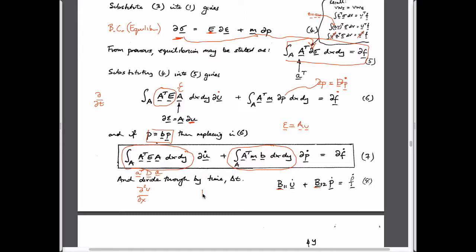Our relationship which defined advective flow was something like the integral of A transposed times velocity times shape function, or the other way around, I can't remember which, over the volume. And that's exactly what you have here. This was indicative of a first order term. It was change in concentration with length, in our case, which here would be the same as change in pressure with length.